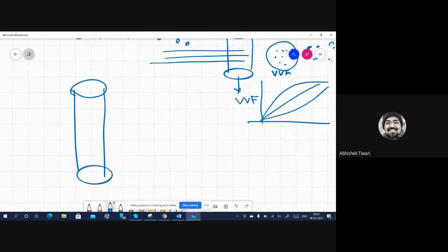again, you take the tensile specimen and load it. So you are applying, let's say, 0.2 millimeters. You just pulled it 0.2 millimeters, and you make sure that the stress has gone beyond yield strength. So it is a permanent deformation. Once it is a permanent deformation, you stop the test. Okay, stop the test, cut it here.